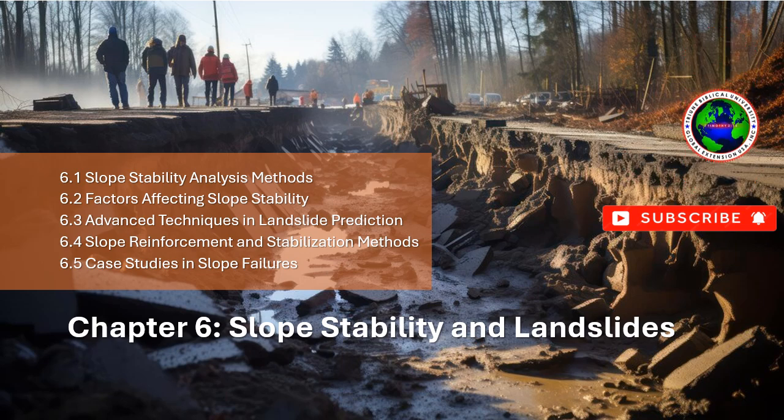Fissures and cracks. The presence of fissures or cracks in the slope material, whether caused by weathering or other factors, can increase permeability and weaken the structural integrity of the slope, making it more susceptible to sliding.